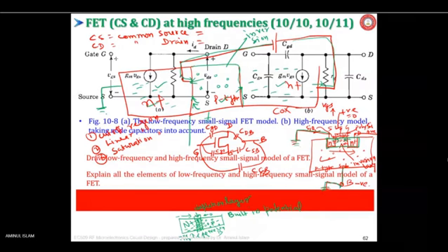Negative ion layer, right? So further, if an electron tries to move, it is going to face a wall of negative ions, and it will be repelled. So initially it will diffuse to some extent, and a voltage will be developed. What is the voltage for Si? This built-in potential is how much? 0.7 volt. Okay, you have studied this in electronic devices, I hope.